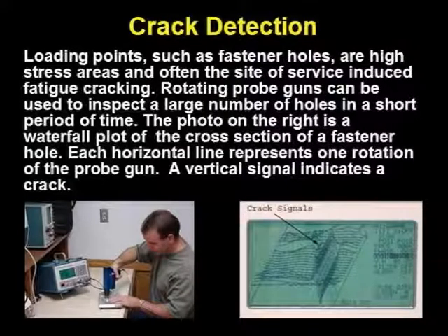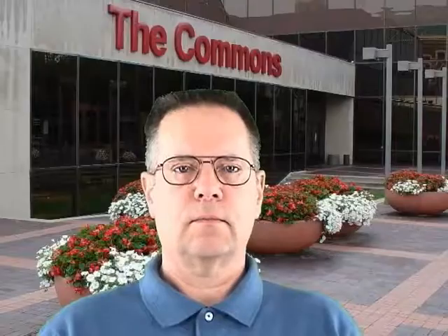Many holes can develop cracks either because of high residual stress, the presence of material defects, or fatigue. Special side-looking coils can be rotated and translated using probe guns to perform hole inspection. This type of inspection has been performed at Cummins for injector nozzles and other tubular structures.